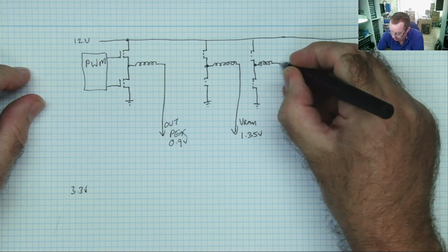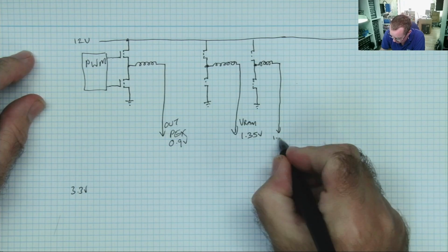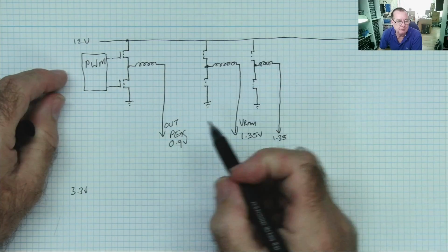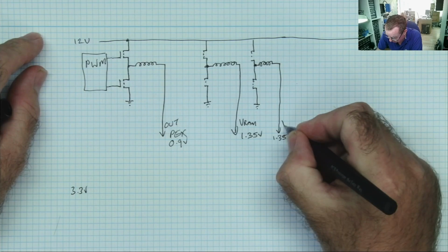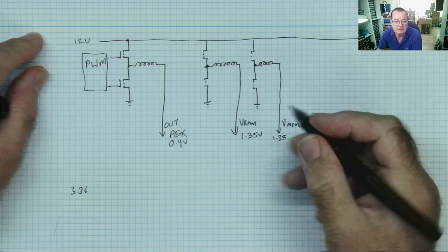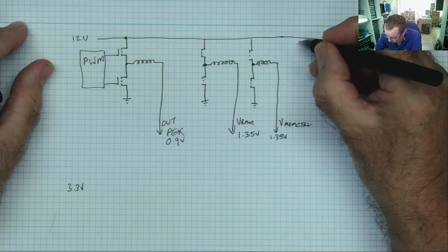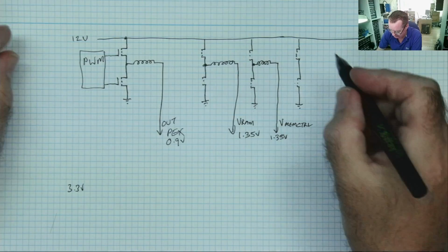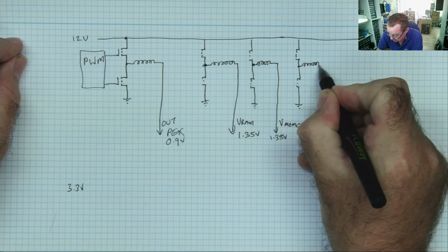This is the supply to the memory controller. This is a similar voltage to this one. And on older generations of RAM, we probably don't have it, it's probably using just this voltage, okay? But this is the mem control, and it's about the same sort of voltage. What else do we have? Well, we have the supply that's driving the circuitry to the HDMI or DVI or similar. Again, maybe not on all graphics cards, it depends on the architecture of the card.